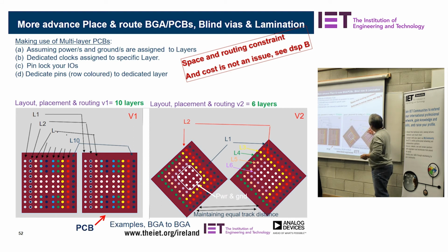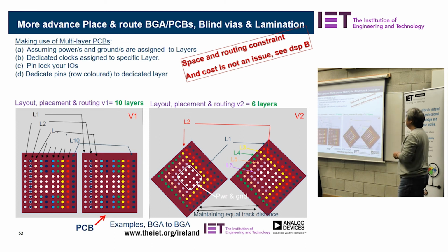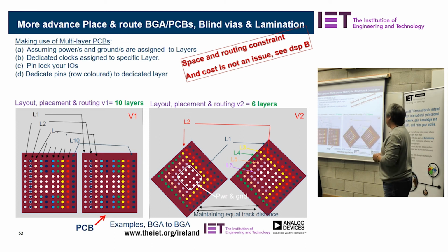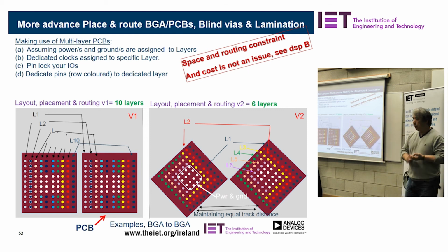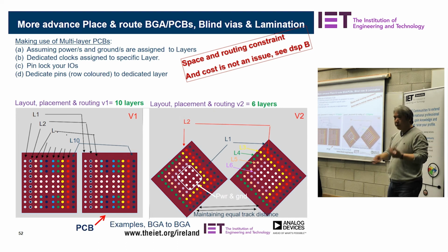So here we take 1 layer from the outer layer, go straight across, and that means that one is done. So the next one, go to the next layer, go down across the next layer. So you have 1, 2, 3, 4, 5, 6 layers to do the job. Okay, so those are some techniques you can employ to do it efficiently, to reduce your cost, and to have less noise, or to try to separate the crosstalk.